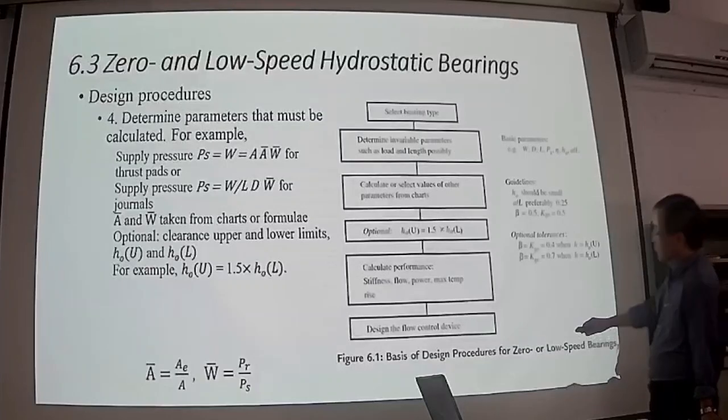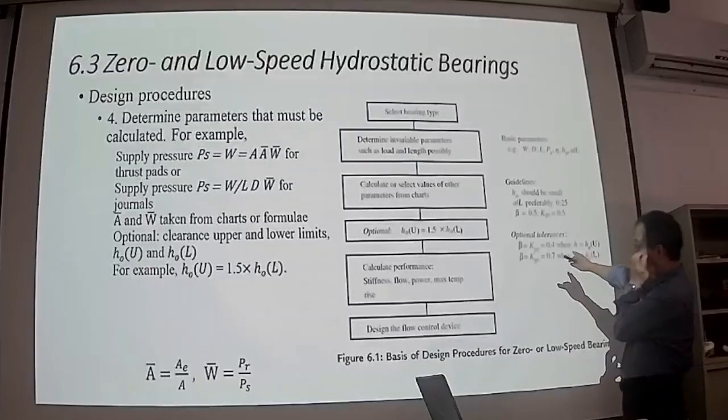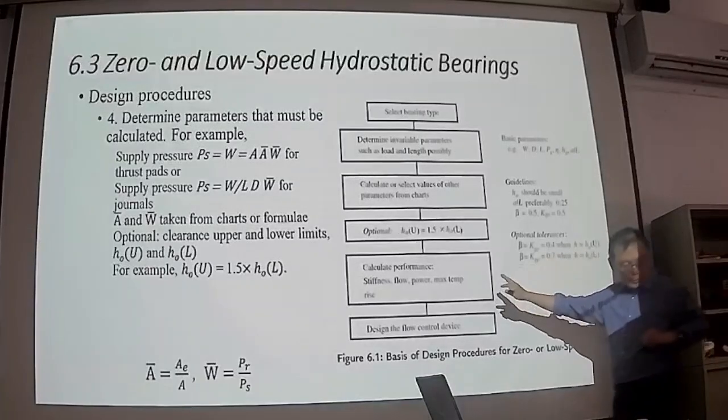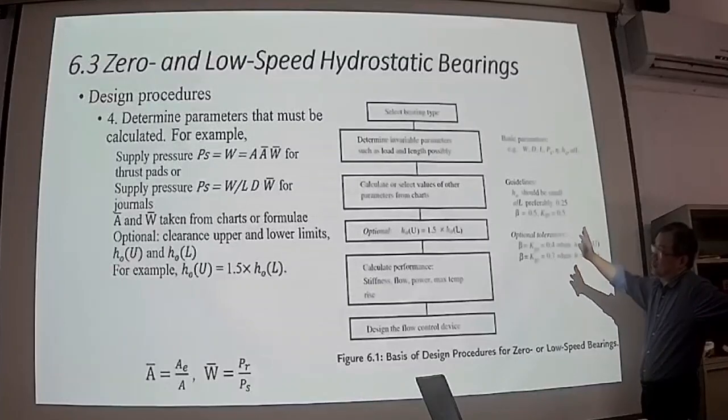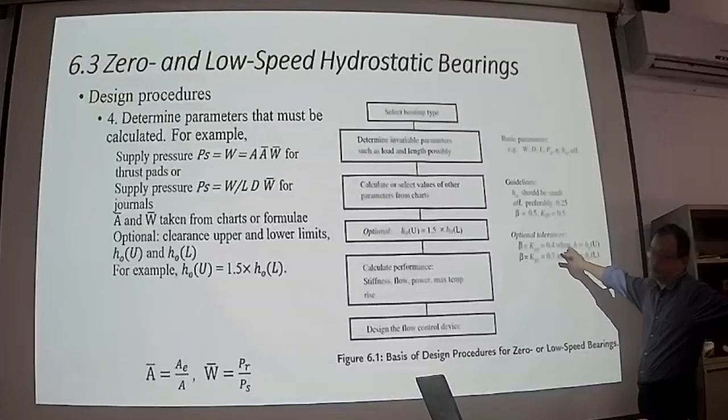So here you need to be careful. If the final film thickness is different from the design film thickness, you need to make some adjustment for your pressure ratio.